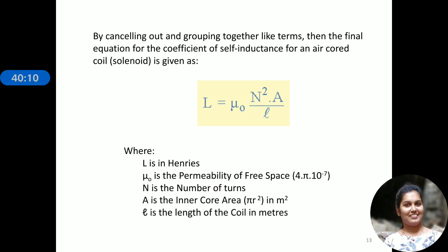If we increase the area of cross section of the coil, or if the length of the coil is increased, inductance will increase. And as well, if we use ferromagnetic material as the core, we can increase the inductance. So these are all the points that can influence the inductance of an inductor. So by varying these points within the given inductor, the inductance value can be changed.